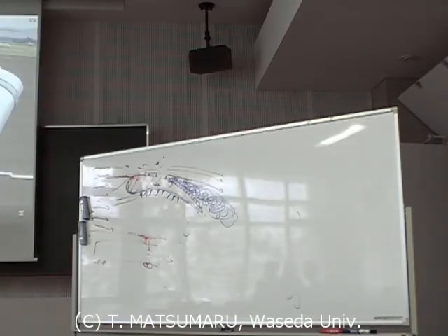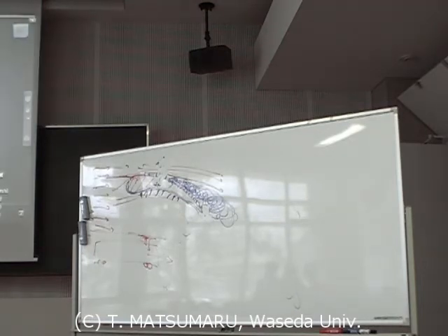Let's take a minute to see how moving air reacts with a solid object. Because air has friction or viscosity, it can act a little bit sticky. Not nearly as much as honey or oil, but it's there. And if you have a free stream of air moving along a solid surface, the air next to that surface gets slowed down by it, and that friction propagates upward. This area of slowed down air is known as the boundary layer, and is why you can never quite blow all the dust off of things.